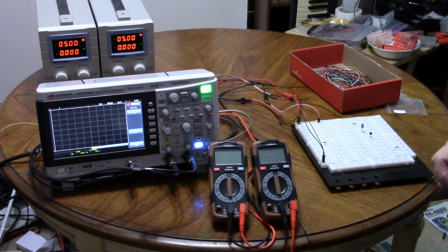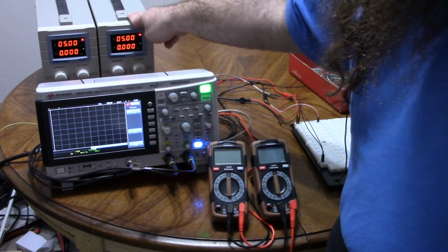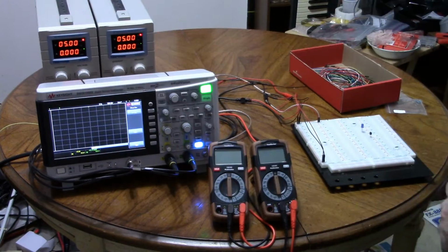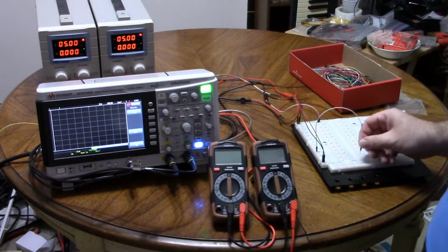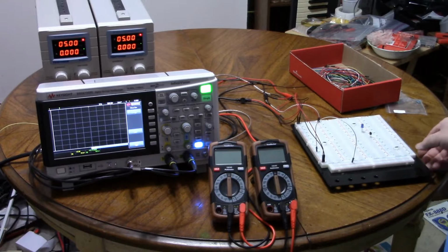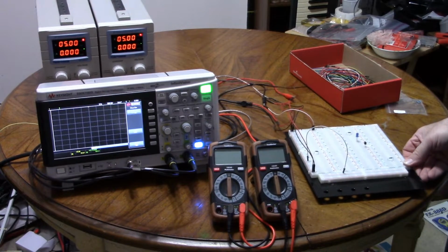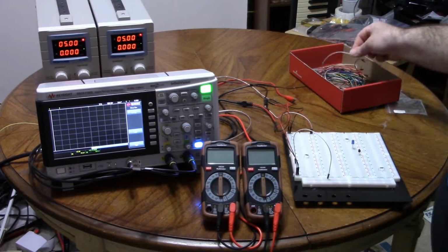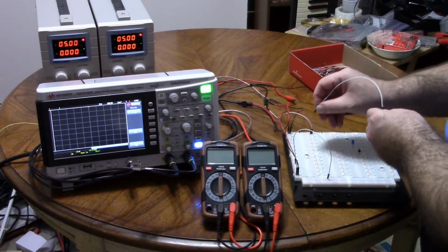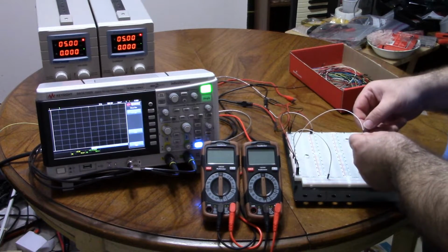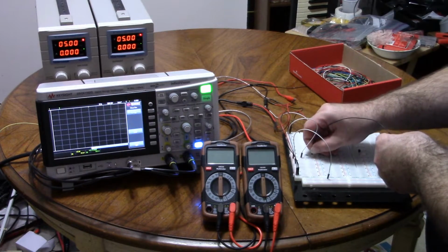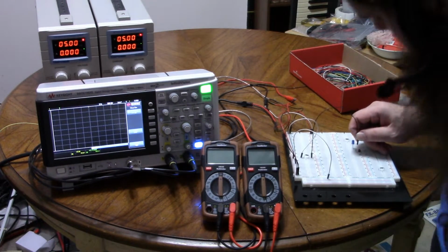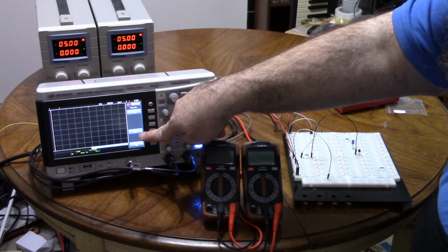So if I come over here, this will be the positive power supply, this will be the negative, and this will be the signal. So I'm going to first connect the negative of the signal to this trace down here, which is going to be my system ground, essentially. My circuit ground, my common reference voltage. Furthermore, I'm going to connect the positive of the signal through a 10k resistor, that's the signal resistor. The output of that resistor is going to go into the base of the transistor. The signal is currently at 0 volts.